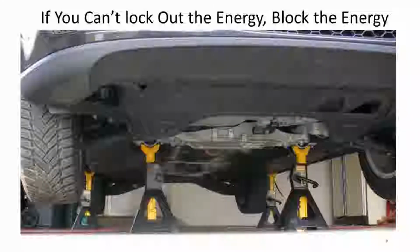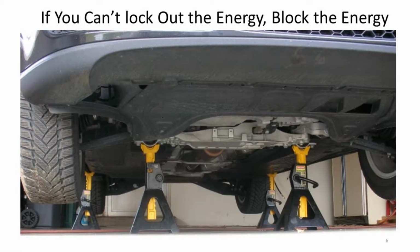Throughout this training, you've heard me say over and over, if you can't lock out a hazard, you have to find a way to block the hazard. I'd like to show you a few examples of how energy, and in this case gravity, can be safely blocked. Many of you already protect yourself at home when you block the weight of your truck or your car by placing it on jack stands. These are great tools for blocking gravity.